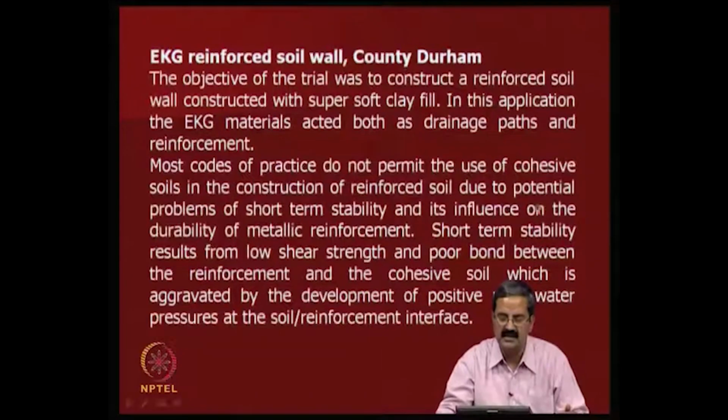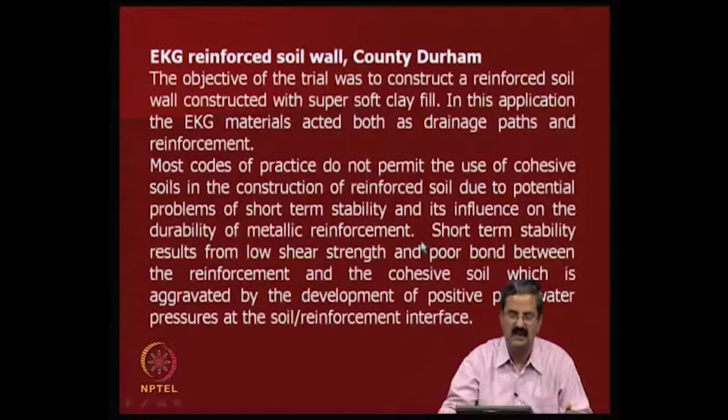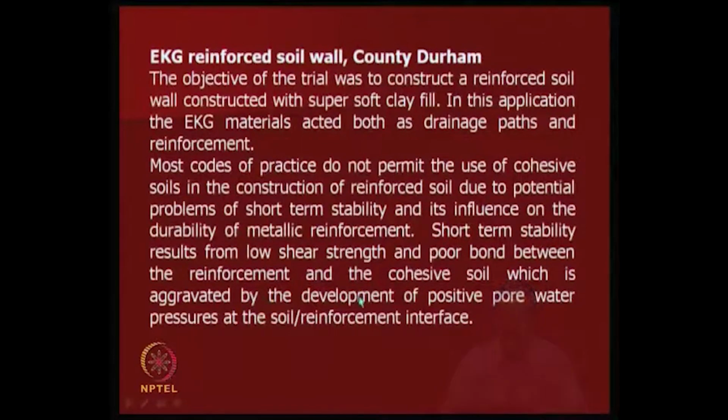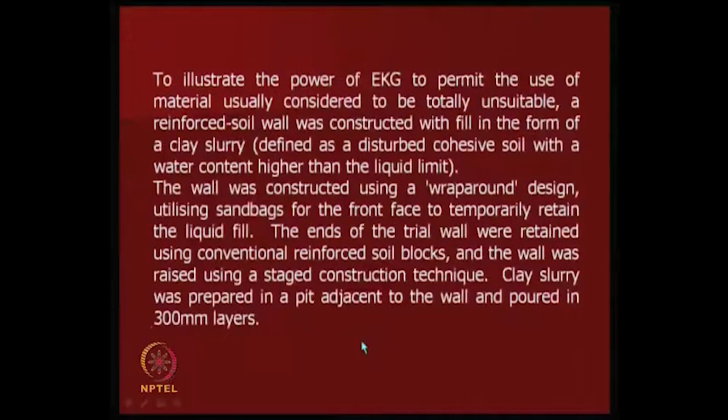So, as I said, most countries do not permit the use of cohesive soils in construction of reinforced soil due to potential problems of short term stability and influence on the durability of metallic reinforcement. In fact, you have codes on reinforced soil wherein you can't use some of these materials, and only sand should be used. If you use clays, the problem is that it is not going to be stable, because there is a low shear strength, poor bond between the reinforcement and soil, and there are so many issues there because of the development of pore pressures at the soil water interface and all that.